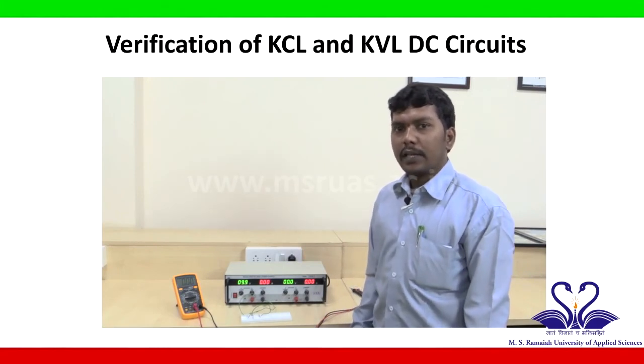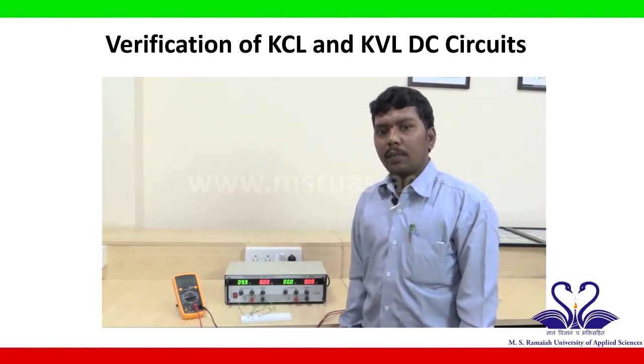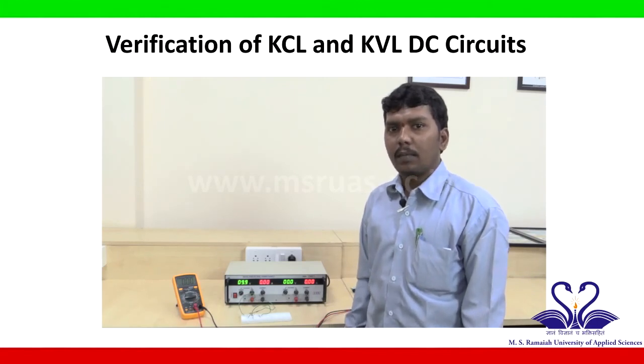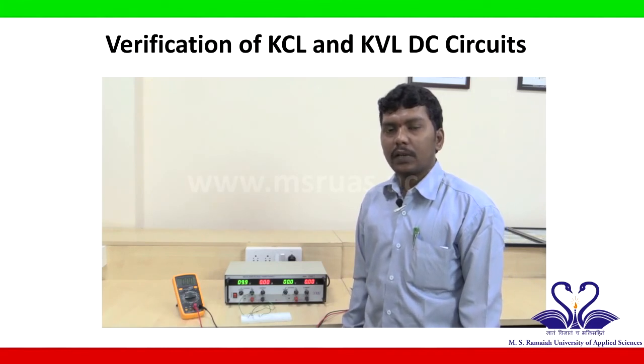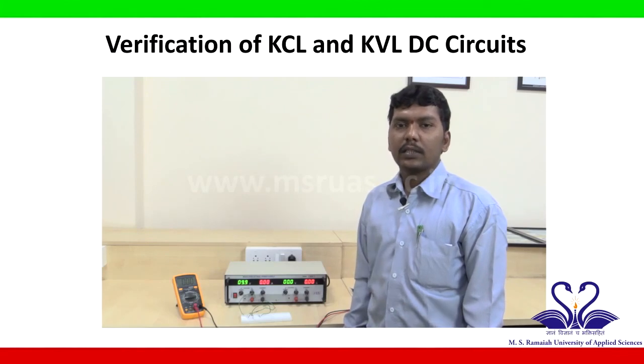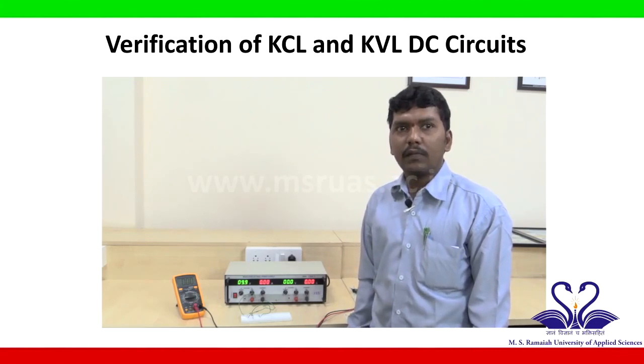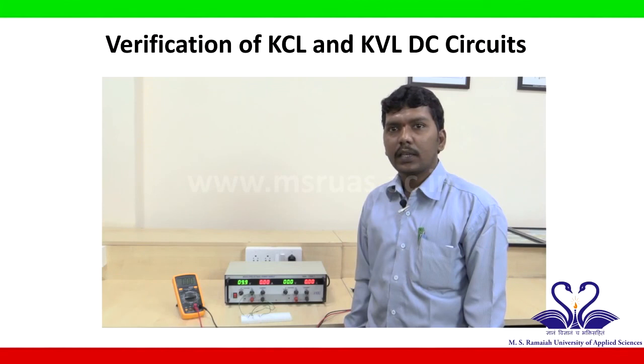So according to the Kirchhoff voltage law statement, the sum of applied EMFs is equal to the sum of voltage drop across the individual resistors. As per the given circuit, the applied voltage V is equal to V1 plus V2 plus V3.